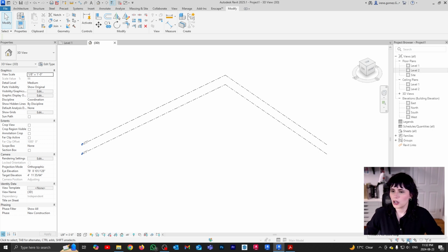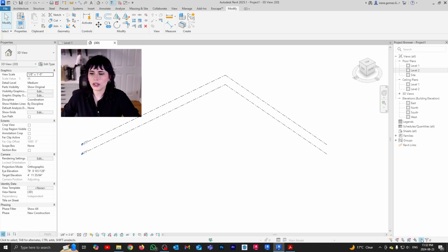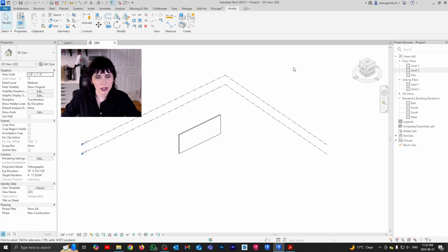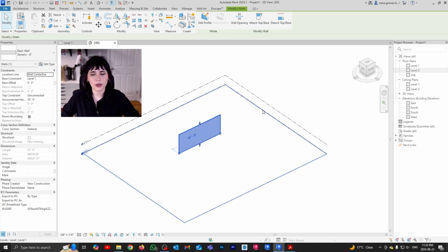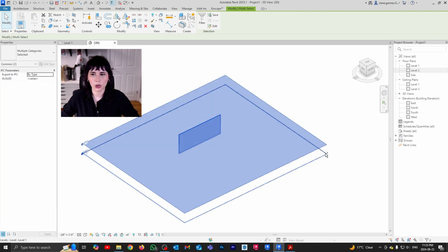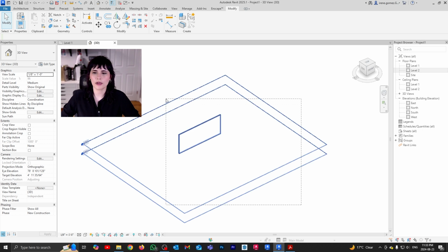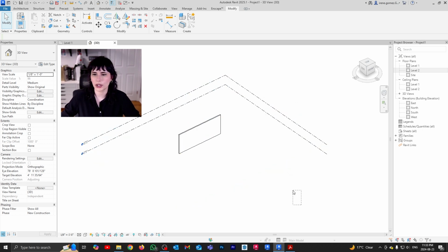Then on the bottom right, we have our selection tools or toggles. So basically these guys are going to give you additional options for selection. There's 2 main things that I really like from this section. Number 1 is the fact that when you make a big selection, and in Revit selection works the same as in AutoCAD in the sense that you can only select one thing at a time. So if you want to add to the selection, you can either hold Control to add multiple elements, hold Shift to subtract from that selection, or you can do selection box. From left to right, you have to fully cover the object for it to be selected. From right to left, you only have to partially touch the object for it to become selected.